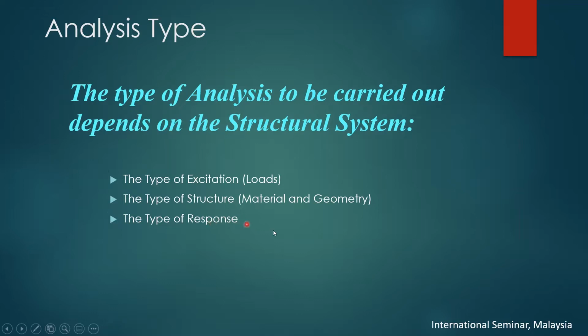You need to see the deformation shape for the floor. Okay, deformation of the shape of the floor comes from the gravity load, right? So the type of response is different. You need to see the deformation of the swaying of the building under wind load. You should go to the wind load direction, horizontal direction, and see the drift of the building. You want to see the torsion, the torque of the building, the twist of the building. You need to see the center of mass and center of rigidity of the building.